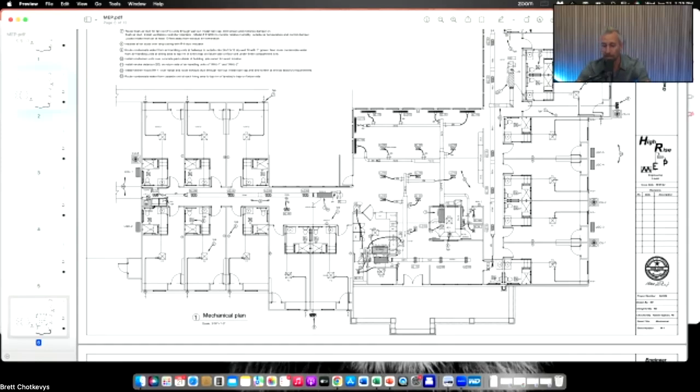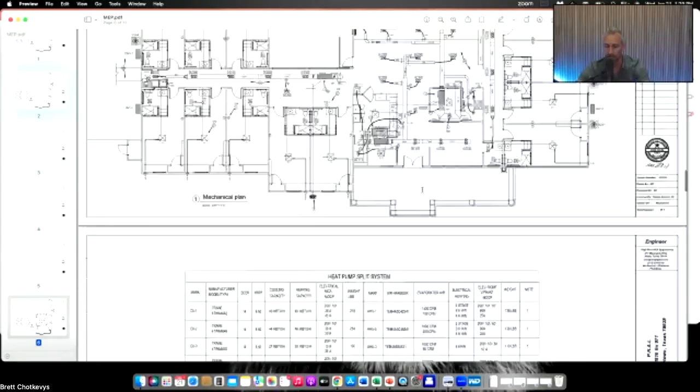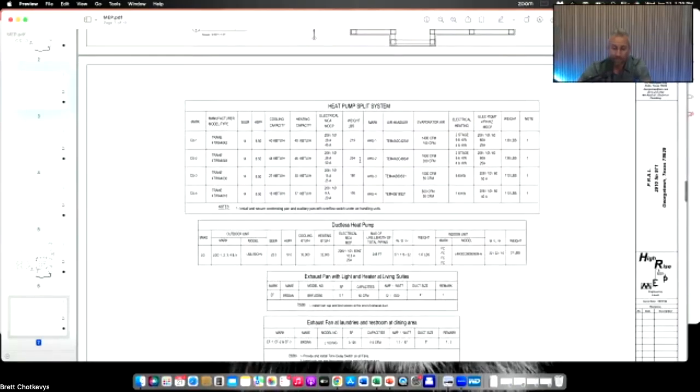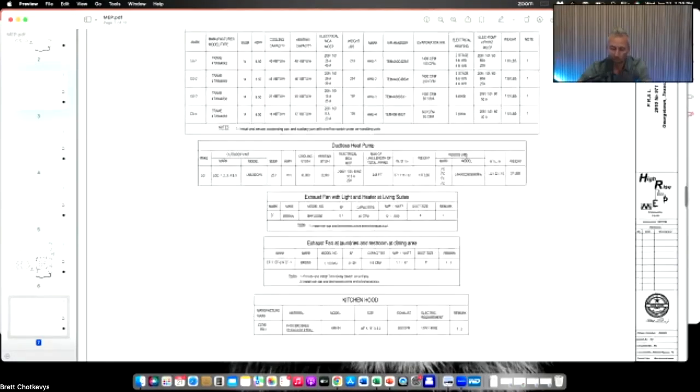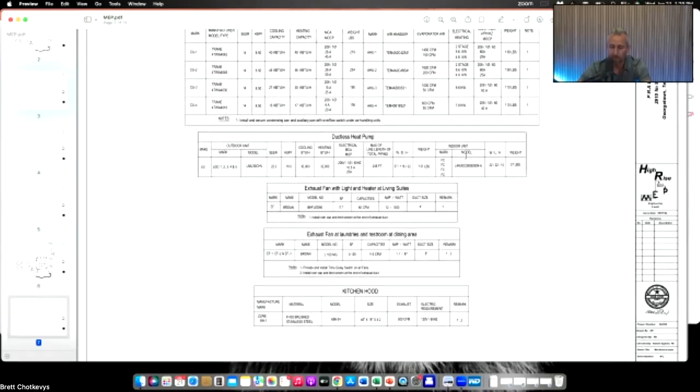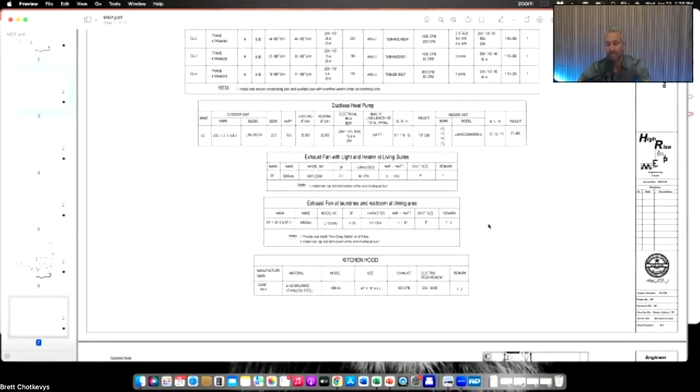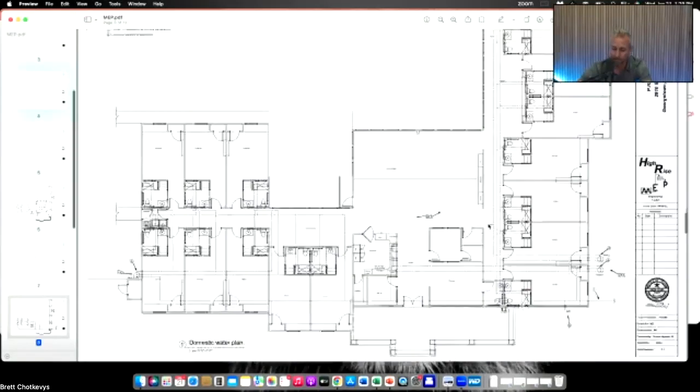And then you need to know, again, your HVAC company can't just throw this in there. They need to know how wide this duct has to be. And then it has to literally be calcs for the whole square footage of the two-dimensional floor plan times the ceiling height to make sure it'll properly cool everything. And then they'll take that and spec out the actual systems. Here's what they're calling by brand and serial number for what model of HVAC system, kitchen hood, same with your water heaters, all that kind of stuff.